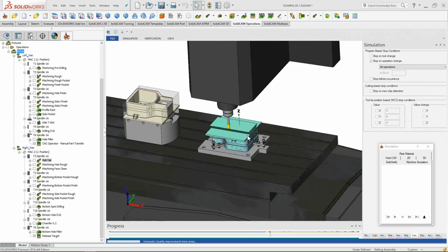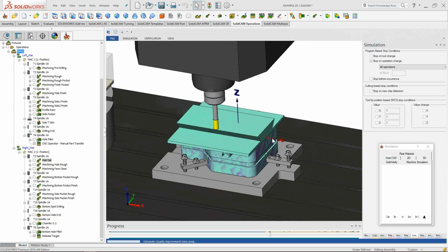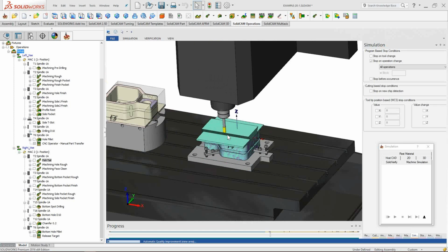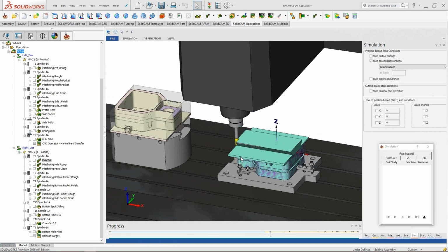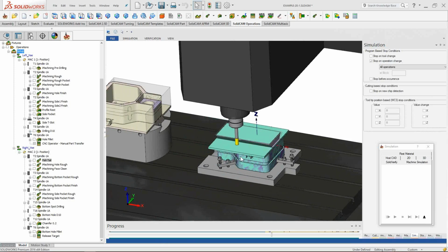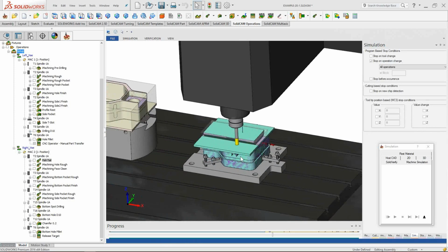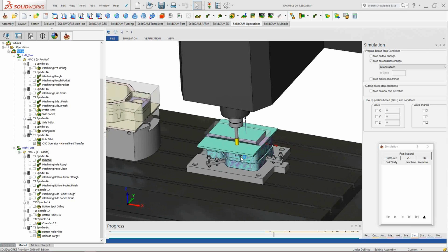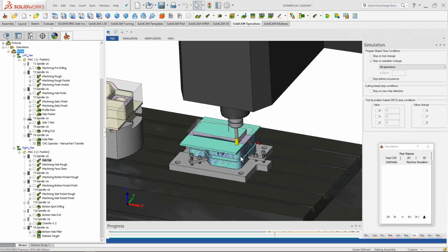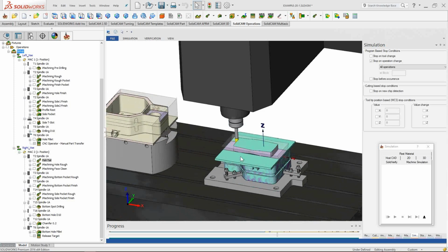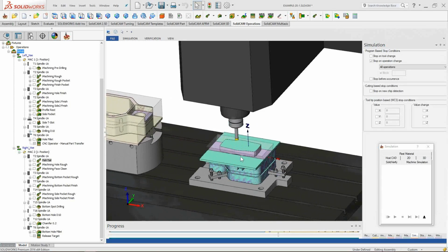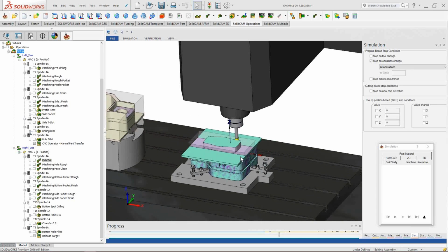And next operation, as you can see, it read our G55 and it jumps to the first operation of the second part, as the iMachining or the fishtail that is here is necessary to clean. And here it is. Very nice feature. So besides the synchronization manager that can be used only in mill turn, here is one example of how you can use it with customers that have, for example, only one milling module.